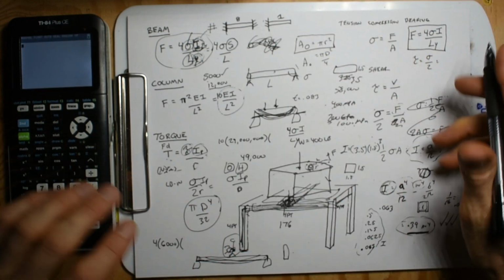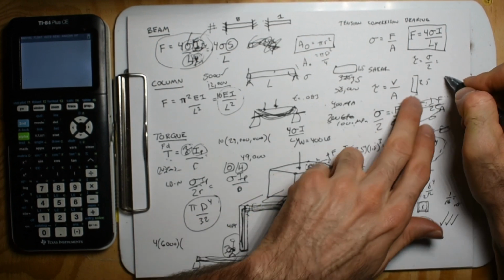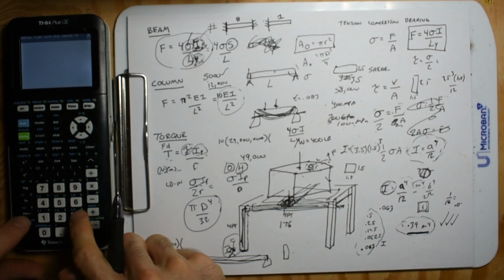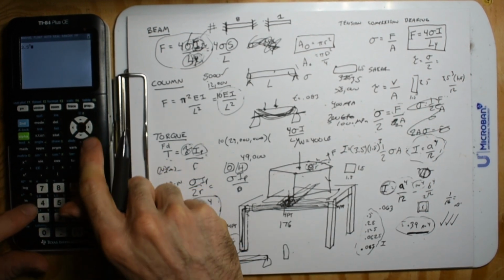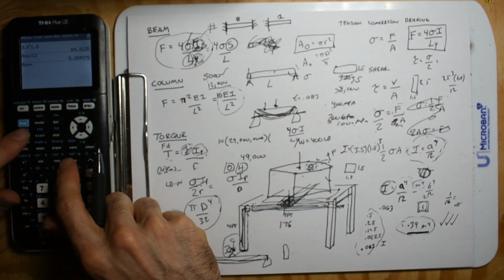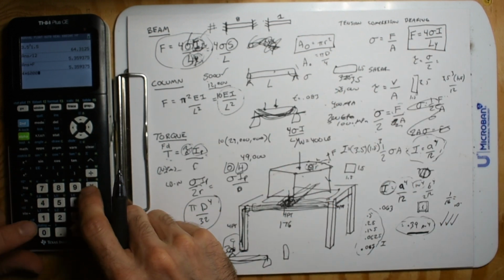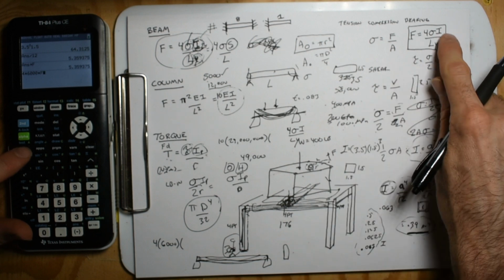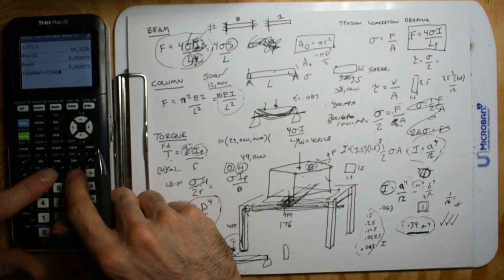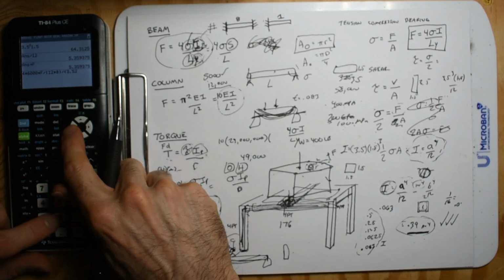And so now when our 2x4 is this way, we got 3.5, 1.5. So we get to go 3.5 cubed times 1.5 divided by 12, and then we got it. We're going to store it as alpha f now. So we got 4 times 6,000 times alpha f for our area moment, divided by 12 times 8, and then divided by, in this case, half the height, which is 3.5 divided by 2.